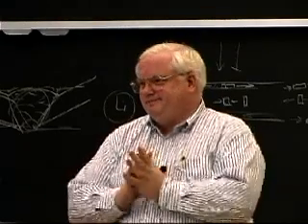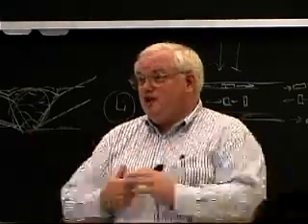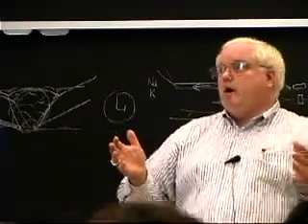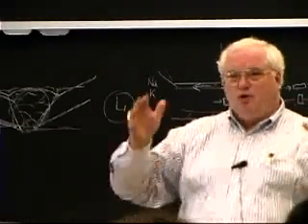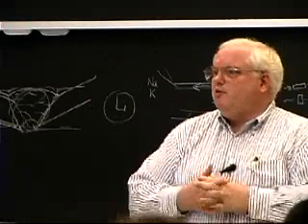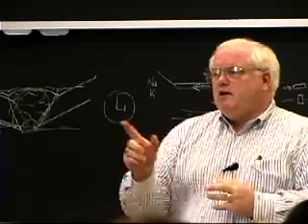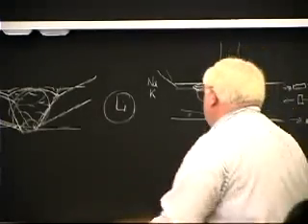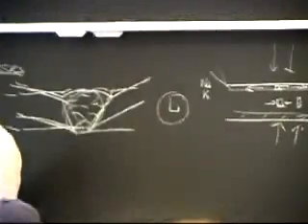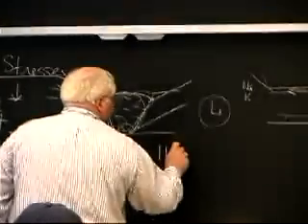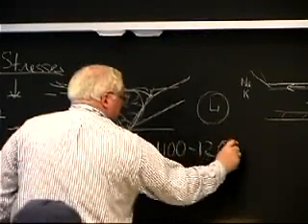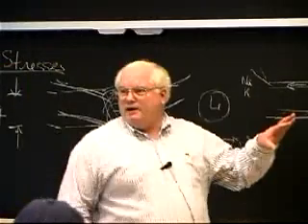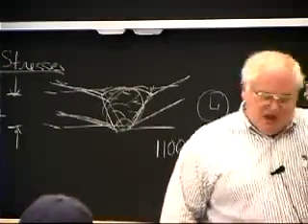We do. You don't put it in a big furnace, although for pressure vessels, they have furnaces that are 10 times the size of this room, and they put a whole pressure vessel in. When do we? The heater is for preheating the steel to keep the hydrogen off. To stress relieve steel, you've got to go to 1100 to 1200 Fahrenheit. That's when the steel starts to soften, lose its strength, okay? And that's when you can relieve the stress.